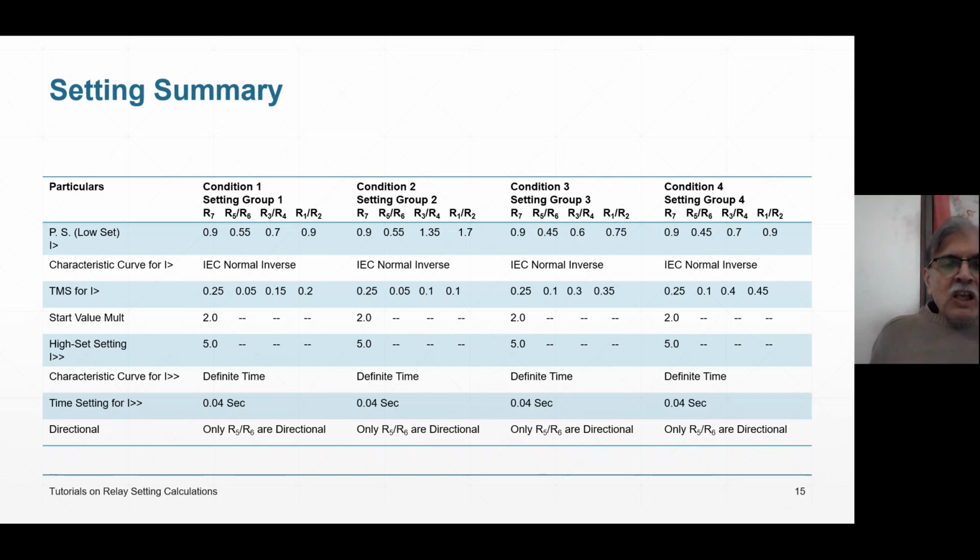Now when I go, the frequency meter is not showing that. It was showing 49.7, 49.8, 49.9. Now it is showing 49.95 or 50. And if it increases, it increases to 50.01 or 50.02. Over or under frequency is not occurring.